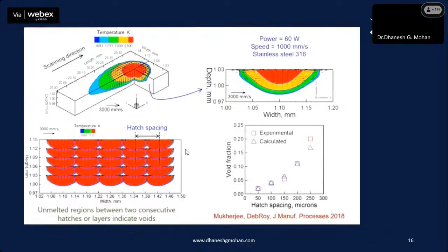And see, these are the fusion defects we mentioned before. In this image, the red area is called the fusion area. In normal welding, we call it the weld pool; nowadays it's called the fusion area for 3D printing. In the bottom image, you can see there is a void in this fusion area because of the hatch spacing. Hatch spacing is nothing but the distance between each pass we are printing.